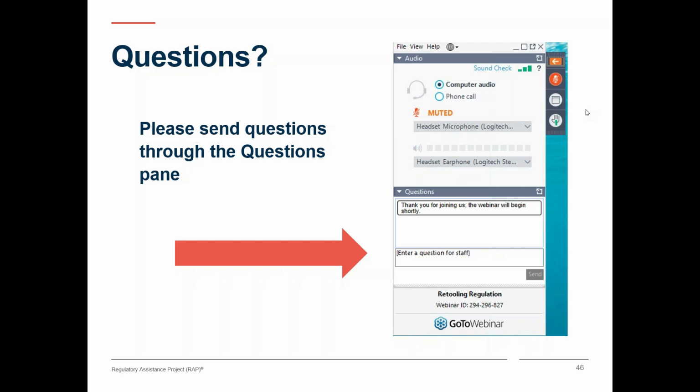Perhaps say right. I don't think Burbank anticipated all of the benefits they're getting from their smart grid investment, but there was no rate increase for smart grid in Burbank because the first thing they did with the system was to run a program called Smart Saver to right size every transformer on the system and then to do phase balancing on the system. And their line loss reductions alone produced enough power supply cost savings to make their entire payment on the bonds that they issued to pay for the smart grid system.